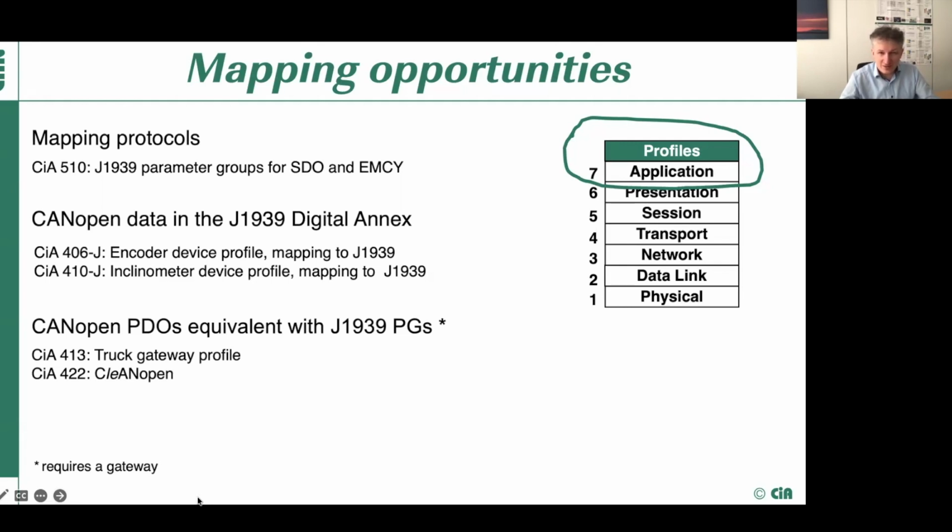We requested them a long time ago from the CiA organization, so they are fixed. This way you can use them for mimicking SDO and emergency communication protocols in J1939 networks, and know which message in J1939 was resembled and how to reconstruct it if needed for the CANopen network.